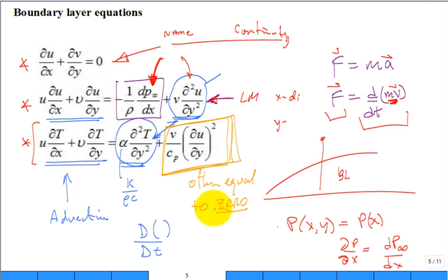But everybody will ask this question. Okay, you're doing an energy balance, but it's only a subset of the energy. It's not a kinetic energy balance. This is a heat balance or internal energy balance. I know it has specific heat at constant pressure, so like an enthalpy balance. But if you have a lot of kinetic energy, you can dissipate some, and it shows up in the heat transfer equation, in the energy balance. Here it is, it's showing up. This is viscous dissipation.